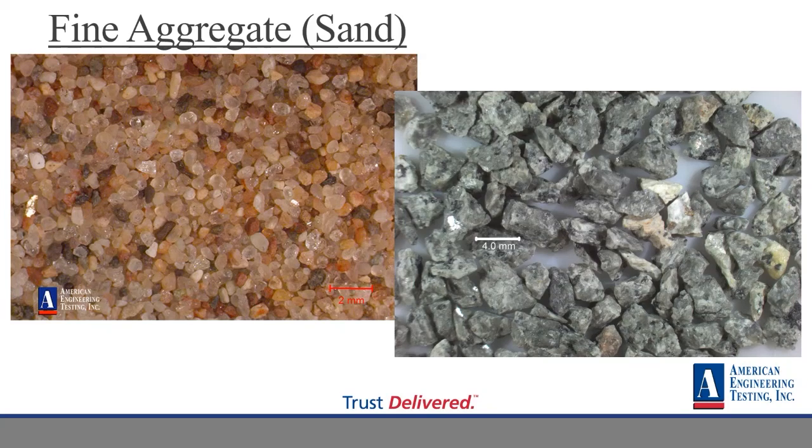I just crossed a granite, I just crossed a basalt, I just crossed a mineral, quartz, feldspar, whatever it might be. And then you'll get a tally and you'll get a weighted percent of how many lithologies and what particles are in there. So the picture on the left, that's a natural sand. Natural sands obviously are going to have a lot more lithologies or minerals in it to identify.